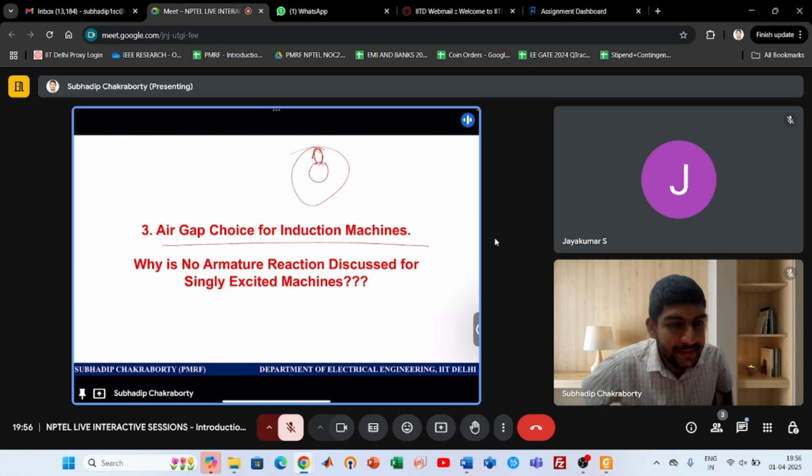Obviously, through the magnetic media we are doing the power exchange, but the air gap has the power. So can you tell me, the transformer and the induction machine both have a magnetizing branch, and the magnetizing branch is nothing but a fictitious or virtual thing which accounts for the coupling field or the induced voltages. We model it by a non-linear inductor. In this case, it is more or less linear because more or less it is air gap. The non-linearity is much more in a transformer because of the least presence of air gap.